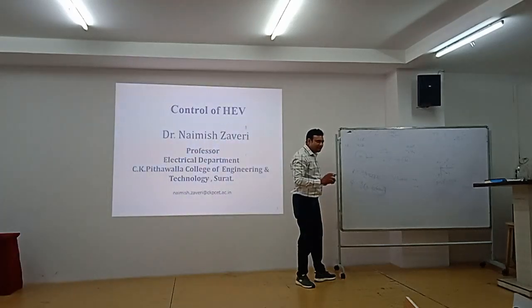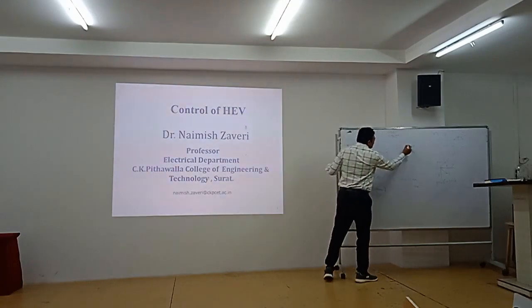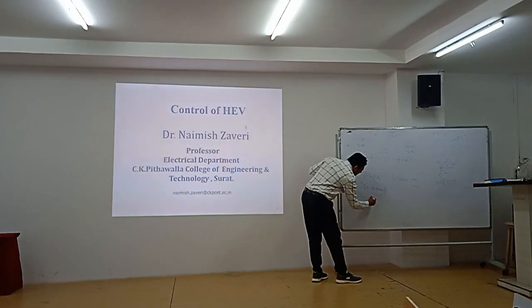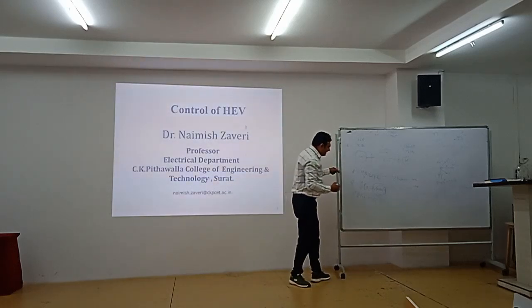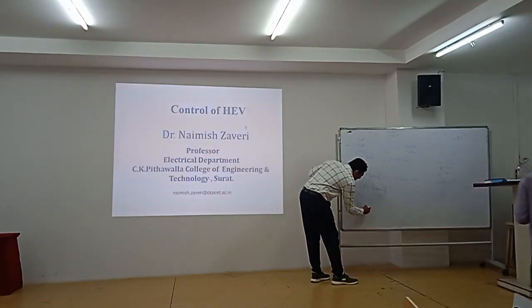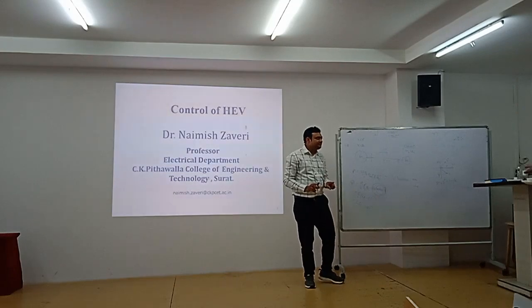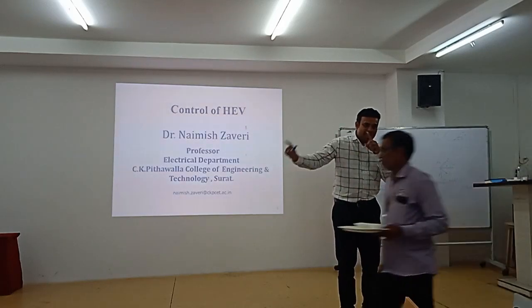Getting? This way you can judge. So here it is, say once it is 1, this is 1.2, right? So 1 upon 1, 1.2 minus 1 into whatever cosine. Next time what happens? Q is equal to 1 upon 1, 1 minus 1.2 into something. So this is voltage dependent, and that active power is angle dependent.